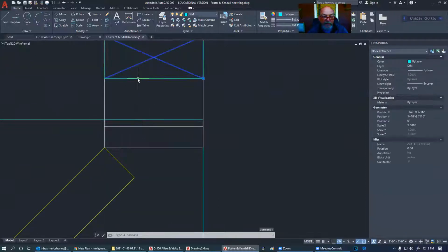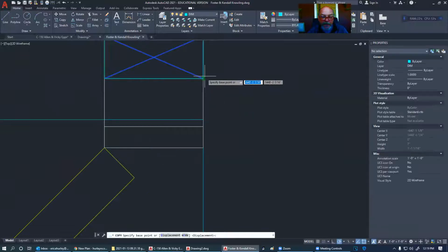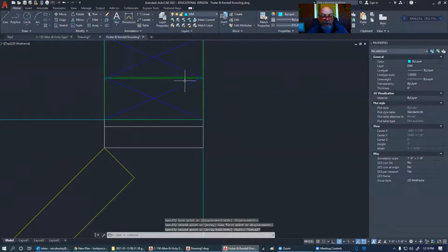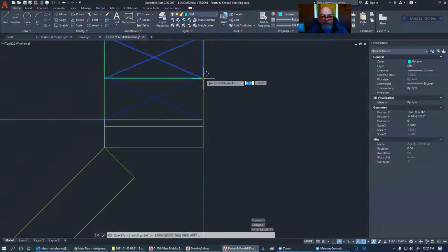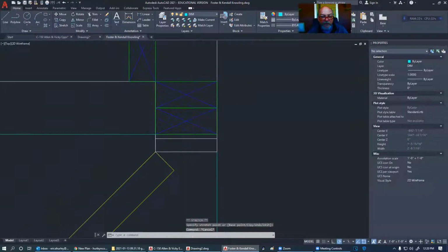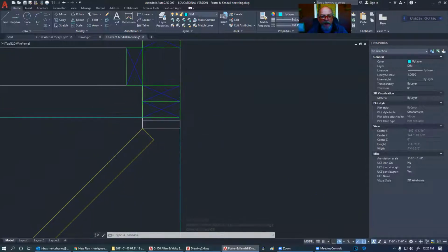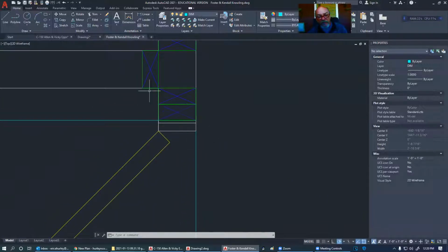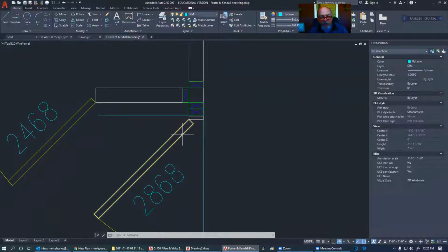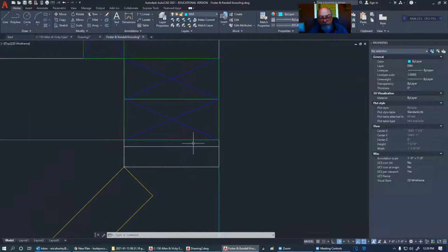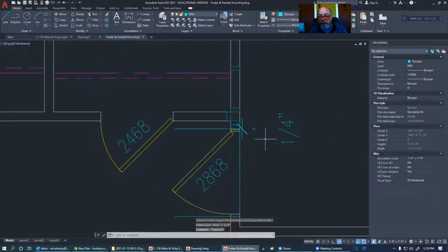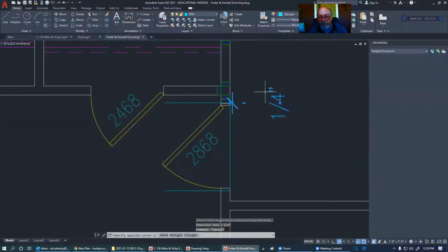This is going to be the first stud that's going to be in here, and I'm going to have a double stud there. And actually, I've probably not given it enough space there. Yeah, maybe so. All right, so how much space is bare minimum? This is the bare minimum that's needed for a door to the wall. So we have 3 inches plus 3/4 plus whatever that is. So how big is that? 1/4 inch. So we have a 1/4 inch shim space there.